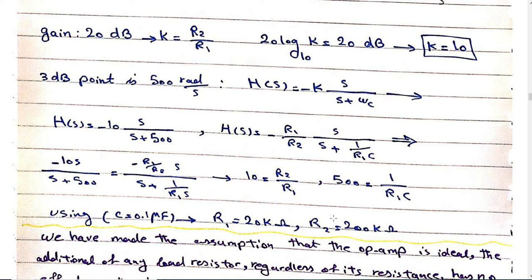Questions? So in this example, C was given. Yes. If we had a question like this, say for a midterm, we get one of the values, the circuit, and the plot? Yes, I will give you the plot. From the plot, you have to figure out the values for K and the cutoff frequency. From there, you can calculate R1 and R2. Clear?